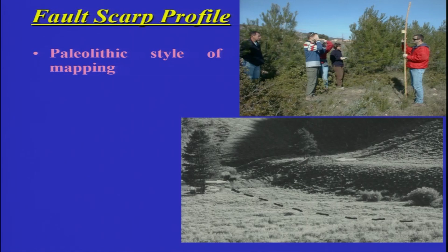And then we came up with total station mapping using high resolution digital data. When we identify the fault scarp using high resolution satellite data, and have demarcated or located this feature in the field, it is most ideal to take the profile across this one. This black dotted line is showing the probable trace of the fault, because this portion is already showing you the retreated or erosional scarp. The scarp got eroded, then the fault on the surface somewhere lies here.